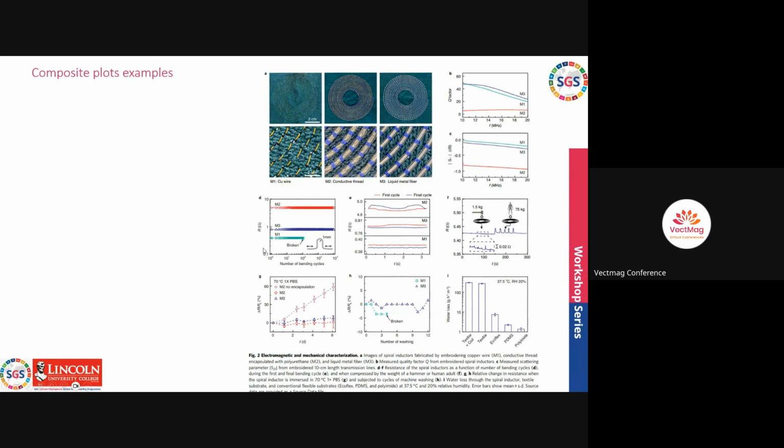And then there is the resistance. Because you are wearing it, what happens if the coil bends with your profile? How is the resistance changing, and how many bending cycles change the resistance? If it is not changing, that is a very good thing. So far from this figure, it is known that it is not changing at all, so it's fine. Then there is resistance across time, in seconds. If there is not too much variation, then this is ideal for application.